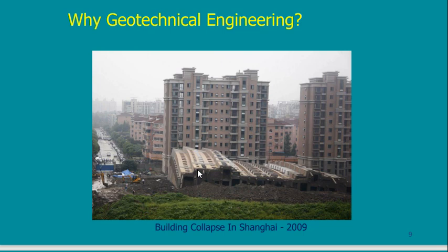That's why I told you hydrology is important in our work. When the rain fell, water started to seep from the high land to the low land, pushing the building. The building was designed on a simple foundation to carry vertical load, but it was not designed to carry horizontal load. So the foundation collapsed and the building tumbled as one piece. It's a big problem.